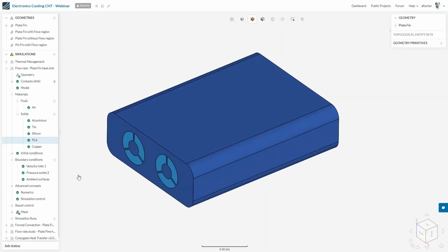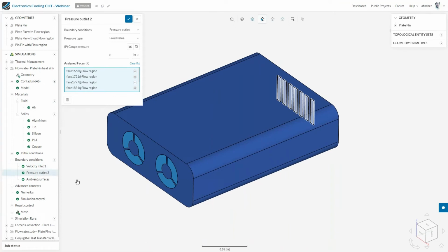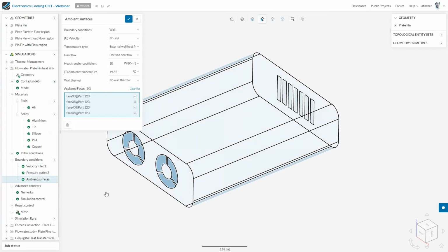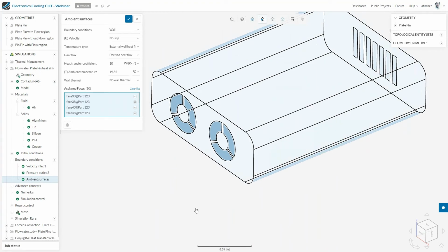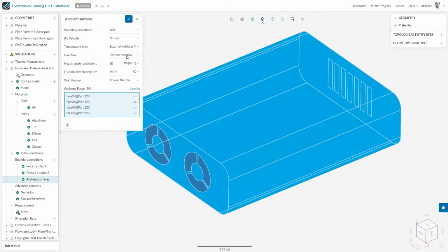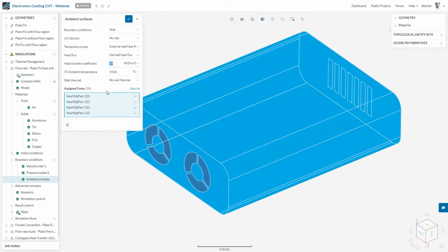Additionally, the boundary conditions are the same as I did in the new setup, but now in this case I also added here the heat transfer coefficient setup. So we put here natural convection boundary condition as a wall on all outer surfaces that are not inlets or not outlets, and put here a heat transfer coefficient of 10 watt per Kelvin and square meter. So usually for natural convection, we have these values ranging from something like 5 to 10 for air convection.